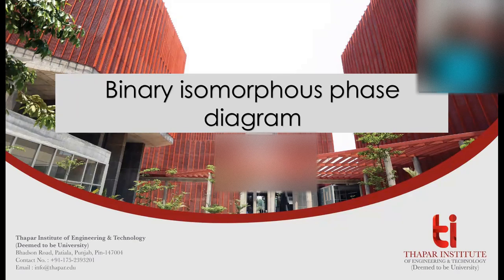Today, like I mentioned, binary isomorphous phase diagram. Binary means there are two components involved. It means when you mix two elements, these phase diagrams will form. Like we have copper, nickel, aluminum, gold, and any combinations of two. Binary combinations. Okay. Iron, carbon. Niobium, silicon, like this you can take.